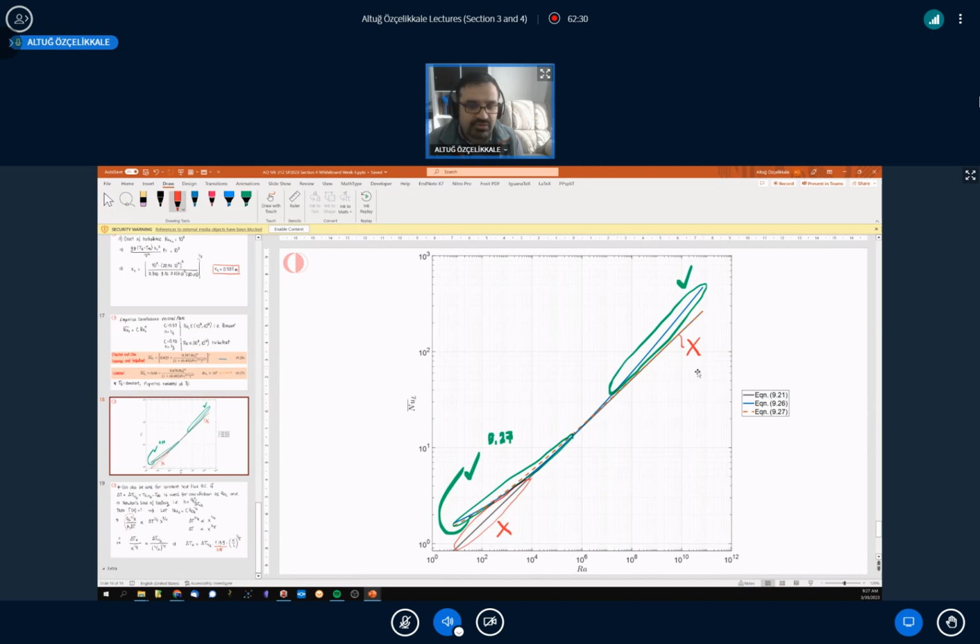So this part, don't use the similarity solution. Clearly, it's for laminar flow. That's a complete violation of the assumptions here. This part over here, we didn't really give you any details on, but you can infer that with the Rayleigh number decreasing, that's essentially corresponding to the speed of the flow decreasing. When we were first defining the Grashof number, we said that's the square of the velocity scale of the laminar flow. And if you consider this, when the Grashof number and Rayleigh number decrease, we are going to have lesser speed in the flow.